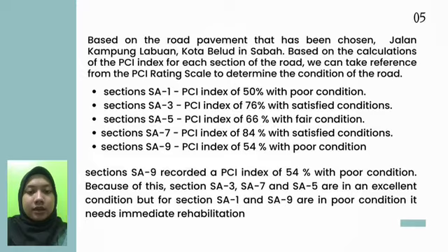While for section 5, the PCI index is 99%, in fair condition. The last one is section 7, where the PCI index is 84%, which is a satisfied condition. And section 9 is 54%, which is in poor condition. So we can say that sections 3, 7, and 5 are in good condition, but sections 1 and 9 are in poor condition and need immediate rehabilitation.